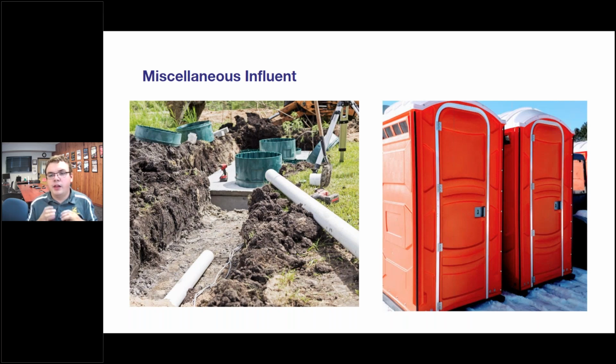Well, the septic waste has its own treatment process, so it's possibly already fairly well treated, in a lot of dead waste material where you don't have a healthy ecosystem happening in the septic system. If you put a huge quantity of that into the lagoon, it can put a big burden on it by having to inoculate it, and it's going to sit for a long time.